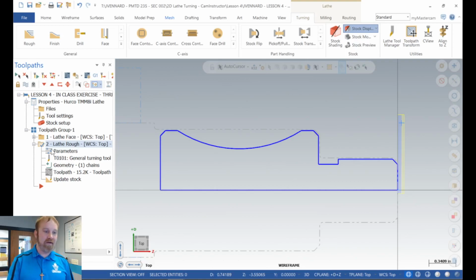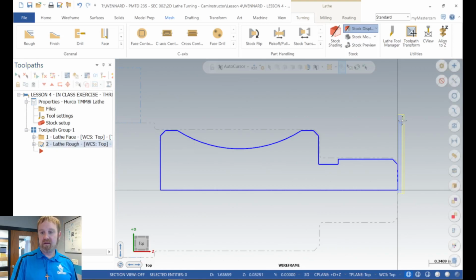All right, carrying on, we're going to remachine down into here to rough this out. We're going to do this with the 55-degree tool. Now I'm going to tell you, on the part that I'm going to give you as an assignment, which is a lot like this part, you're going to have to go to a 35-degree tool. But you're going to use the ones out of the default library. You'll have to go to a 35-degree tool to get down into the features.